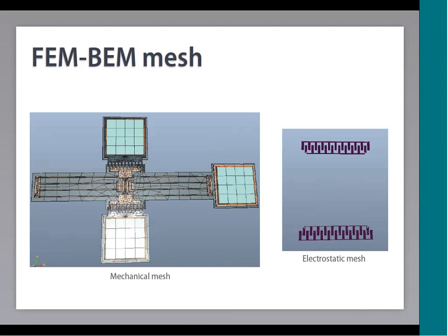Within our simulator, we also have a coupled finite element and boundary element method. This really helps to increase the accuracy of the simulations, specifically for MEMS devices, as well as speed up the simulation time. The basic principle is a mechanical mesh coupled with a separate electrostatic mesh using the boundary element method.